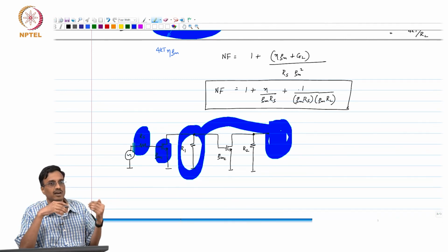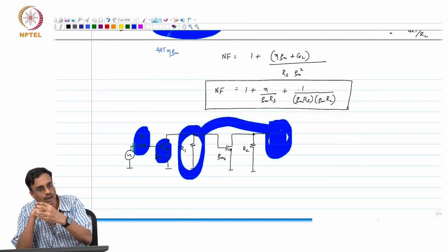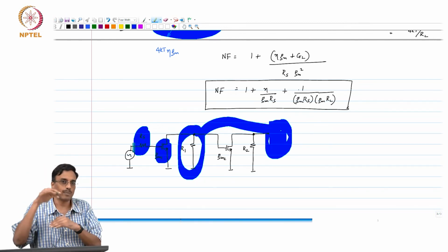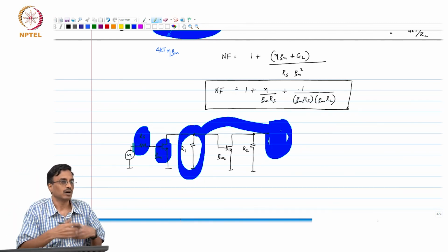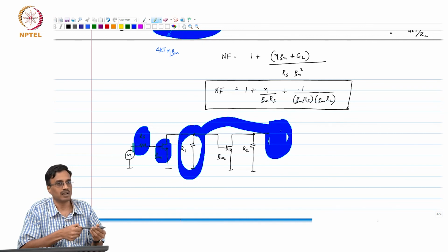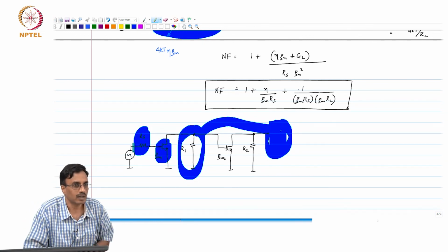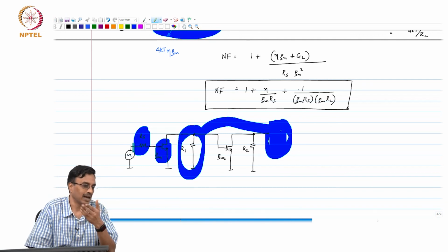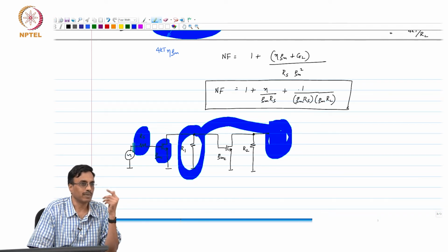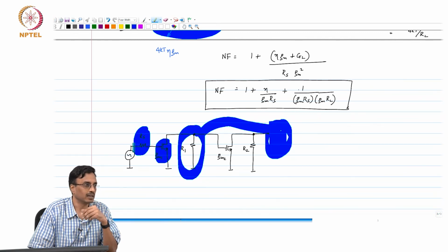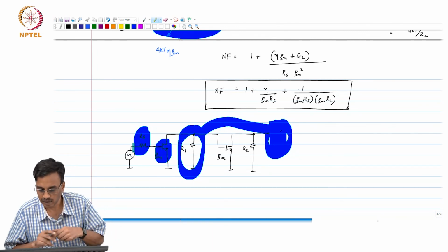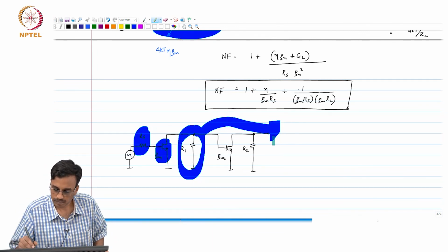And as you keep traveling down the chain, the signal is getting bigger and bigger. So, which would you worry about distorting the signal a lot? Well, yeah, the last stages are the ones which you should be primarily worried about as far as distortion is concerned, and the first stages are the ones that you would be worried about primarily for noise, right? And that's how it goes.